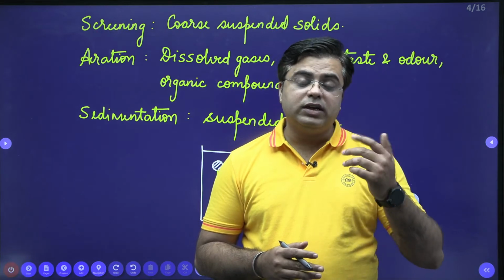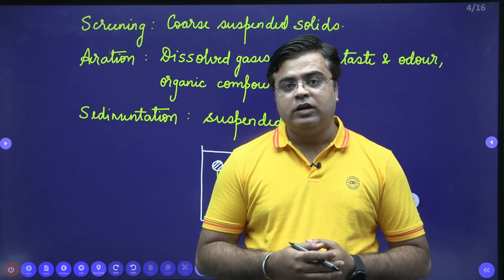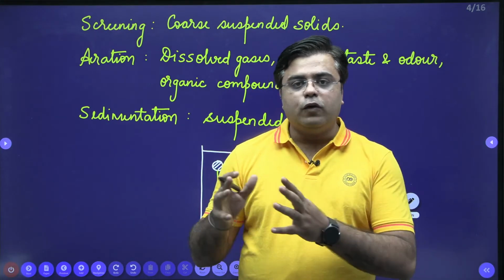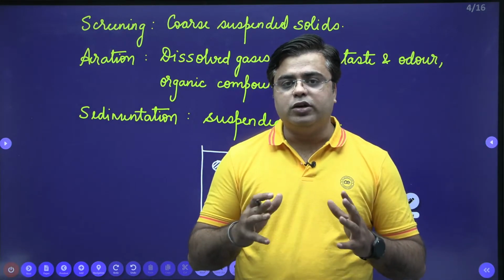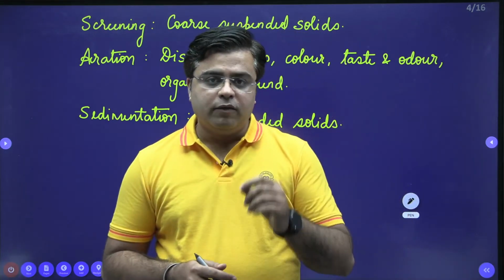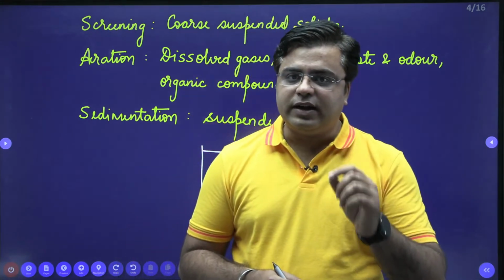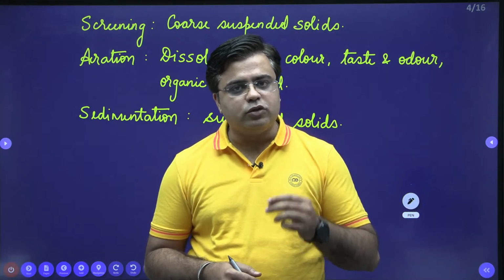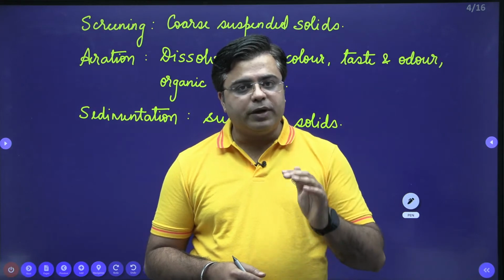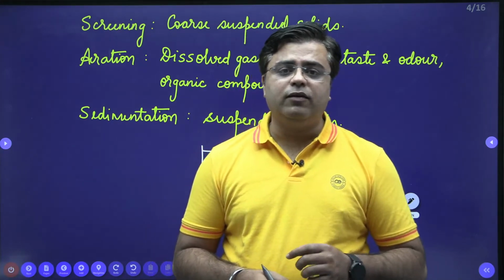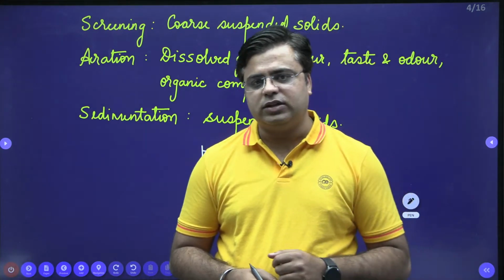For tier 1 cities, it is more than 50 lakhs. So the amount of water required to fulfill the demand of this population is huge. Whenever we are going for raw water treatment, one primary concern is that treatment should not involve much cost. So we prefer those techniques in which operational cost is less. Sedimentation is one of the techniques where there is almost negligible operational cost.